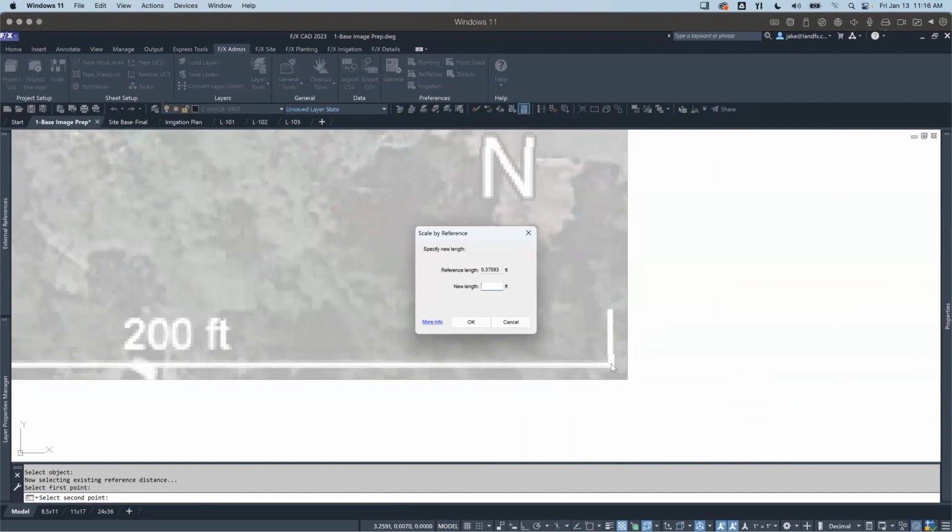So I would not want to try to scale this image off of a parking stall, especially from an image perspective. The larger two points that we can click that are kind of arbitrary, where we don't have a snap point with a known exact distance, the better, because everything will be closer in their relative distances in the long run.